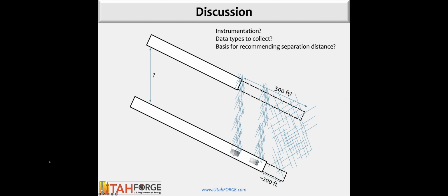A concern we've been looking at is if we depressurize that extraction well too fast, and if there's any pressure support in the fractures, we can essentially close them down and cause ourselves a more serious problem. So we'll have to let it pressurize up and then slowly bring the flow rate out.